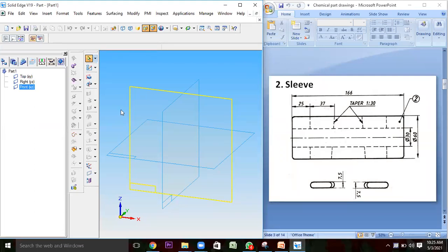Suprit. Yes, sir. What is the dimension from this upper end to lower end? 60 mm, sir. It is 60 mm, right? Now, if I travel from this point to this point, then what will be the reduction in the dimension? 30 mm, sir. From here to here, I'm traveling 60 mm, not 30 mm. I'm traveling 60 mm. And if I travel 30 mm, then reduction in the horizontal dimension will be 1 mm.